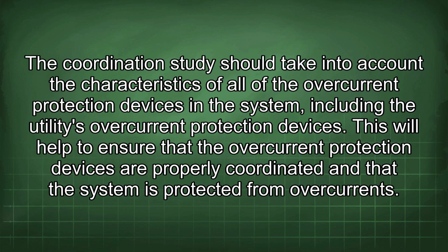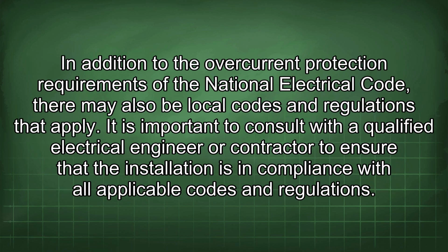The coordination study should take into account the characteristics of all of the overcurrent protection devices in the system, including the utility's overcurrent protection devices. This will help to ensure that the overcurrent protection devices are properly coordinated and that the system is protected from overcurrents. In addition to the overcurrent protection requirements of the National Electrical Code, there may also be local codes and regulations that apply. It is important to consult with a qualified electrical engineer or contractor to ensure that the installation is in compliance with all applicable codes and regulations.